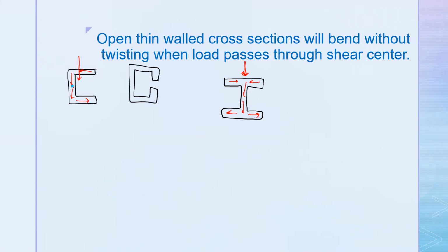Now, if I'm taking the moment created by the shear stress in this member, don't consider the force applied to it. I'm just looking at what is happening within the member. We have this vertical distribution of shear, which is going through that point I'm taking the moment about, so that doesn't create any moment. We have these two flanges that are equal magnitudes but in opposite directions. That's going to create a couple, which is going to create moment. So this is not an equilibrium.